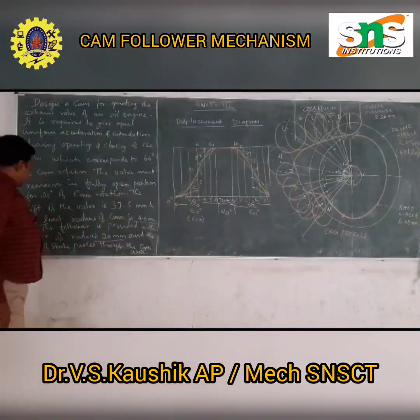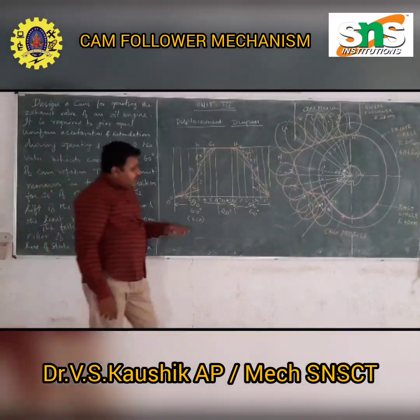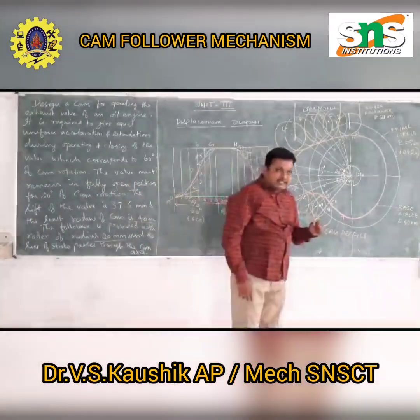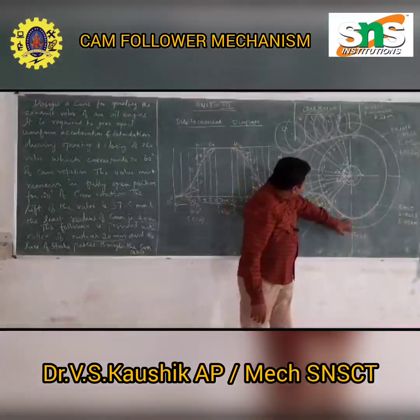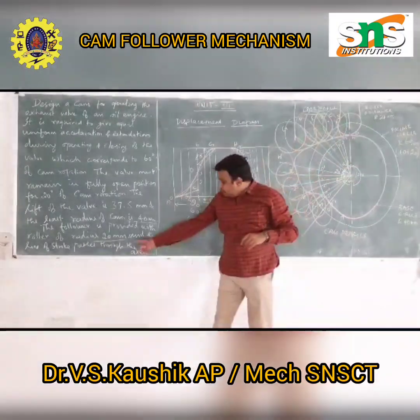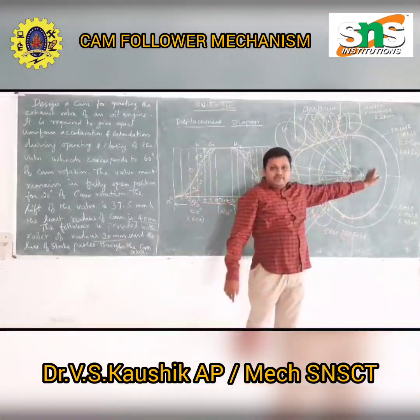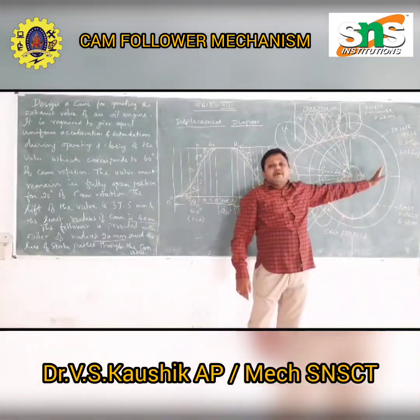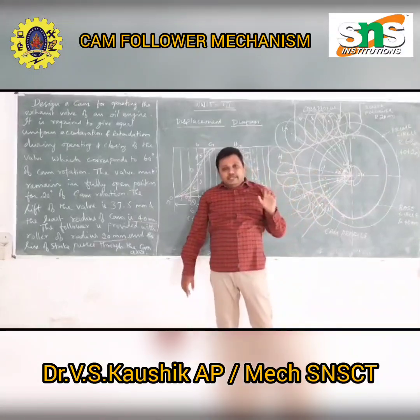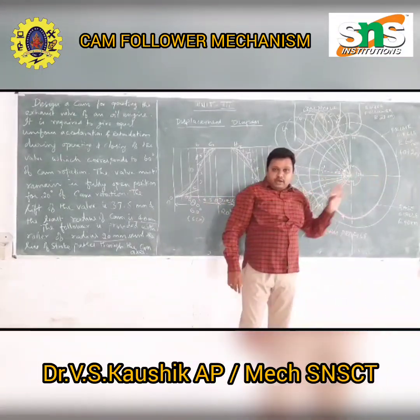And the line of stroke passes through the cam axis, which means the follower remains as such. If the line of stroke is said to be 10 mm away from this or 20 mm away from this, that is offset. That is called the offset position. Okay, now we are clear.